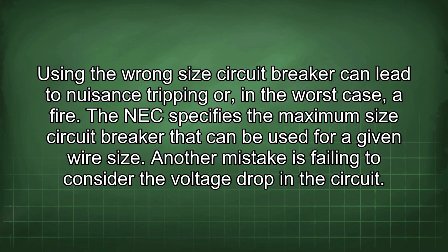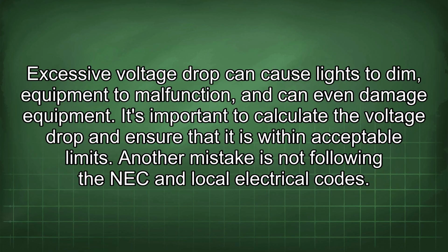Another mistake is failing to consider the voltage drop in the circuit. Excessive voltage drop can cause lights to dim, equipment to malfunction, and can even damage equipment. It's important to calculate the voltage drop and ensure that it is within acceptable limits.